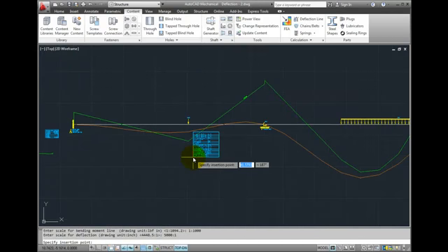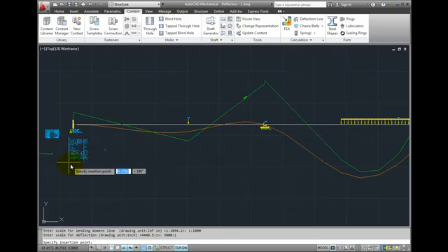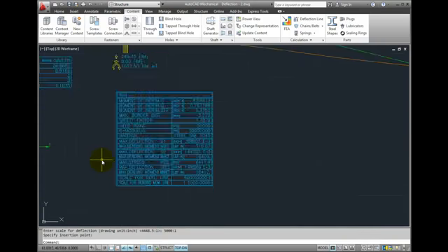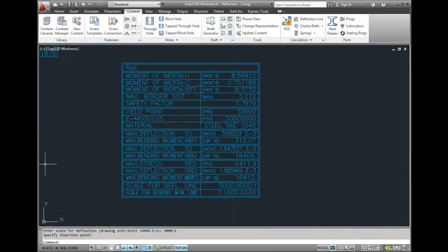I now place a resulting block. So we have our bending moment and our deflection line results. And if I zoom in on the result block, you can see that I have information such as a repeat of the cross-section area with a factor of safety. In this case, we're almost at 8 to 1 factor of safety. What these calculations are based on for as far as material properties, and then information such as the maximum deflection in the two directions, as well as the maximum stress.